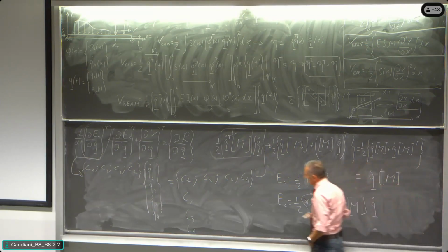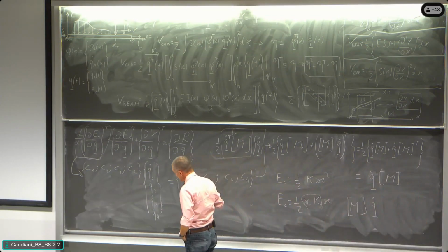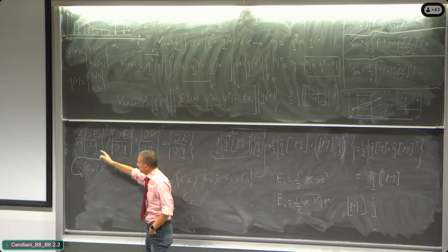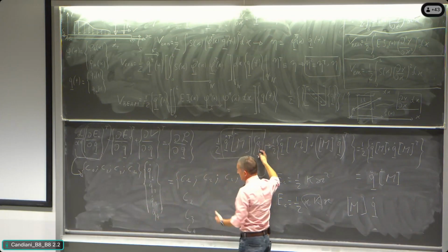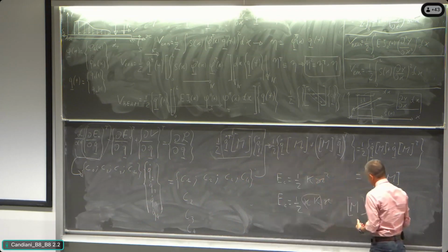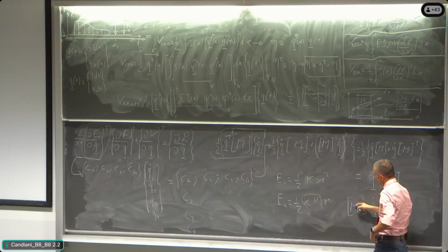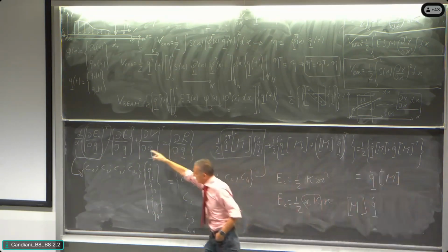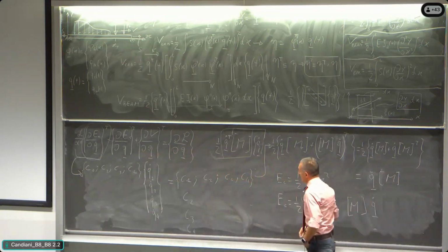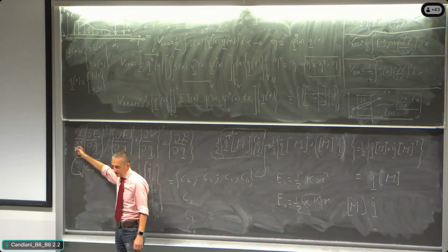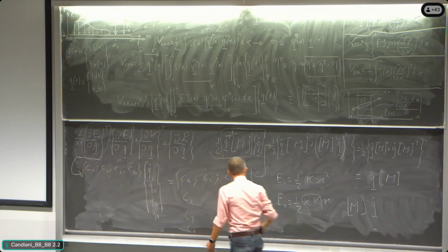So all the time that we are working with quadratic forms, both kinetic energy or potential energy, the derivative with respect of the vector external to the quadratic form itself is making, as a result, the mass matrix itself multiplied by the vector on the right side after having done the transposition. All right. At this point, we say that the Lagrange operator is asking to do the derivative with respect of time. The mass matrix is not function of time.